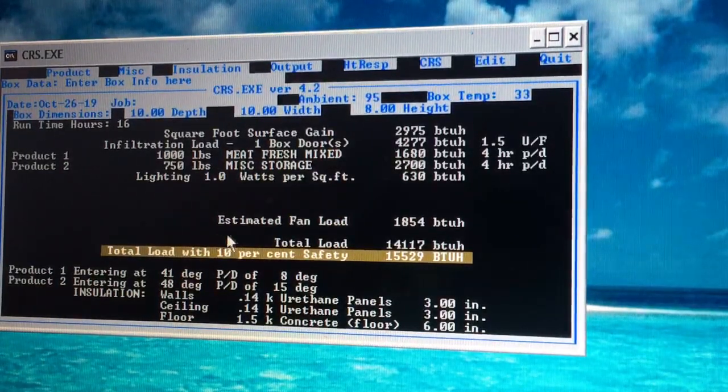And your really important stuff is how much you want that compressor to run on a hot day. If it's 100 degrees out, I don't want the compressor running any more than 12 hours of that day. I like my compressors to run 20 minutes on, 20 minutes off.